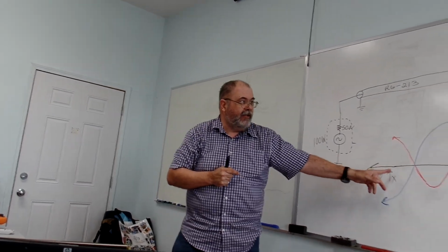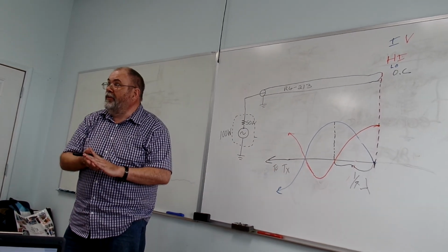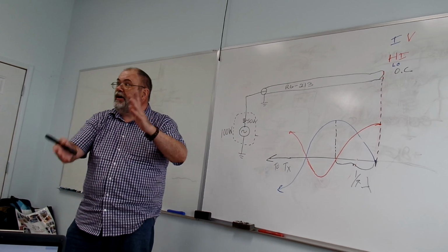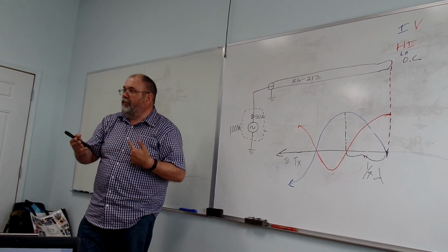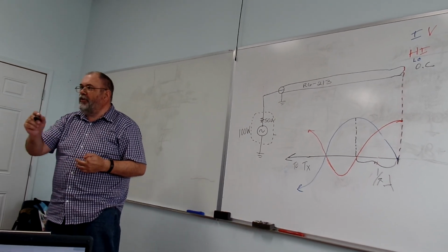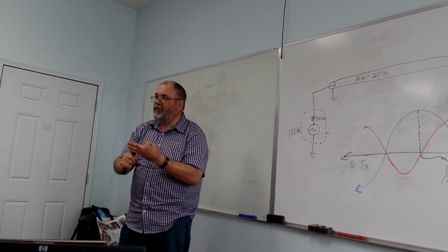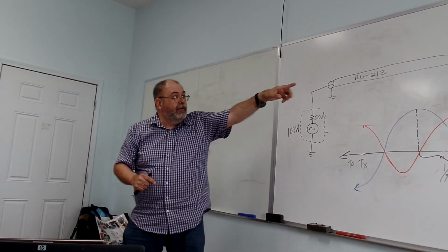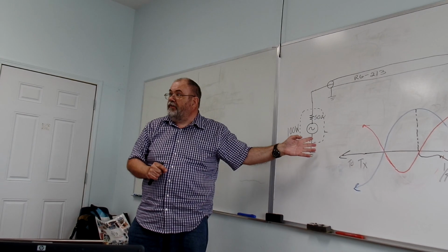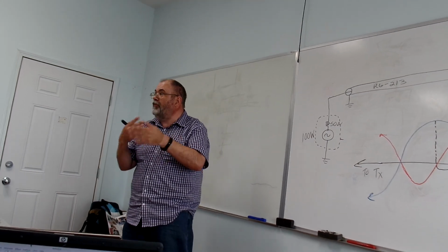If we go back another quarter wavelength, it's going to be back to an open. It'll flip again. If we go back another quarter, it'll go back to a short. So basically, if we go an odd quarter of a wavelength, so 1 quarter, 3 quarters, 5 quarters, 7 quarters, 9 quarters back, all the way, that open becomes a short. Isn't that cool? We completely flip the impedance.